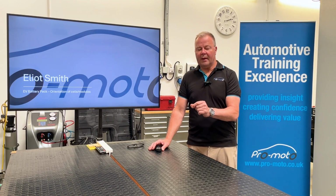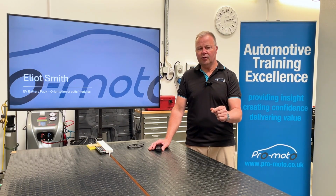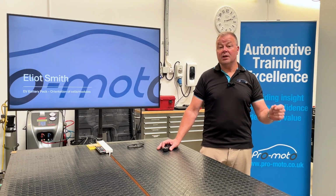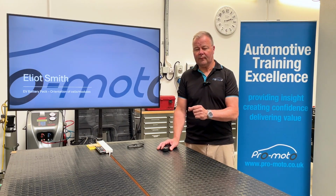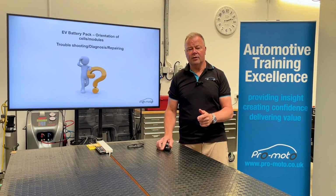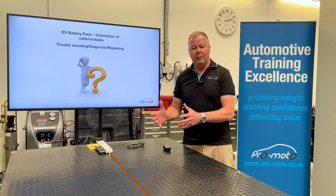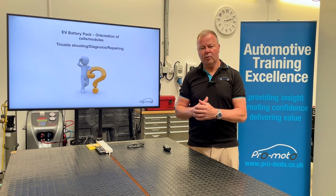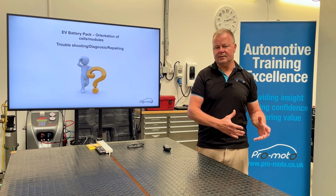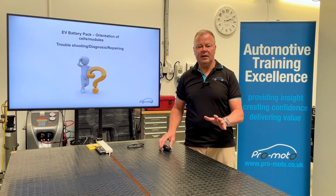Today I thought we'd talk about troubleshooting batteries and the little hiccups, hurdles and curveballs that might come your way trying to troubleshoot, diagnose and repair batteries. One of the things is battery orientation. As we know, there are a lot of cells inside a battery. They can be in series or in parallel, but when diagnosing a battery, if we see a fault within it, maybe some imbalance, we need to understand what it is, where it is, and how we locate it.